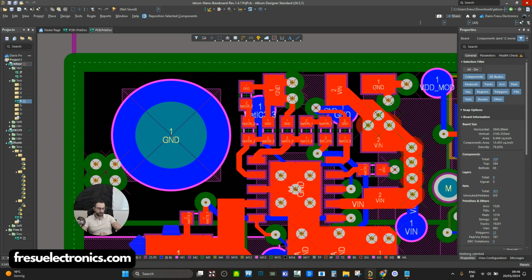So we have to think not only in terms of resistance, because if we just thought about the resistance of the copper, then the problem would be solved much more easily. But we have to think also about the inductance and the capacitance that we have in between. The most important for us though is the inductance between the traces. Why is this important? This is important because first of all we have some transient currents. So this means that we will have a certain frequency connected to this switching.